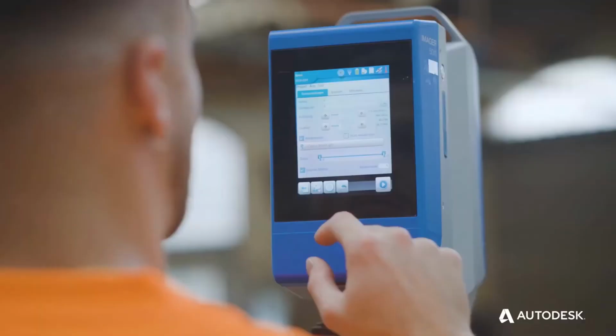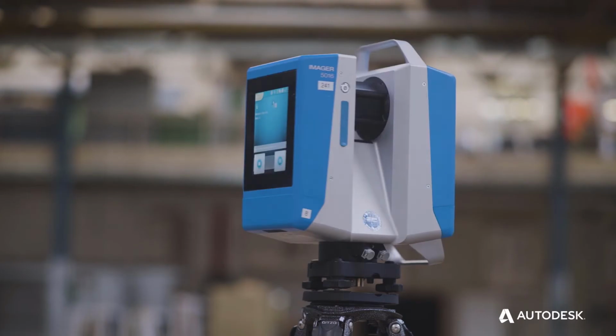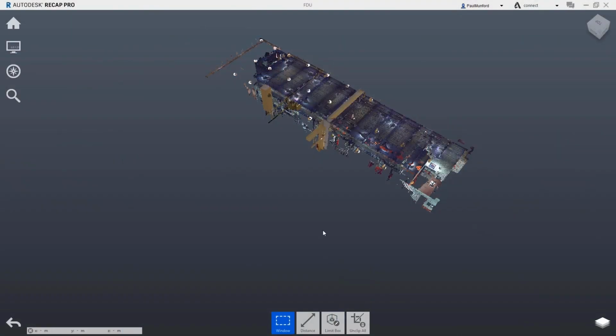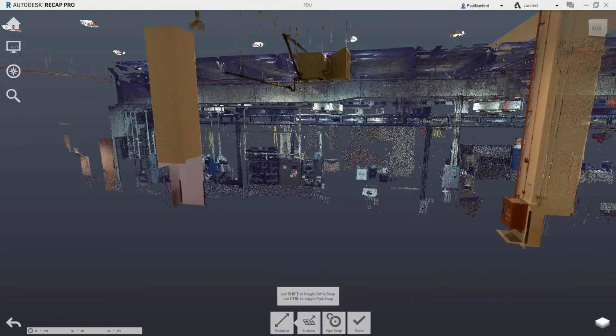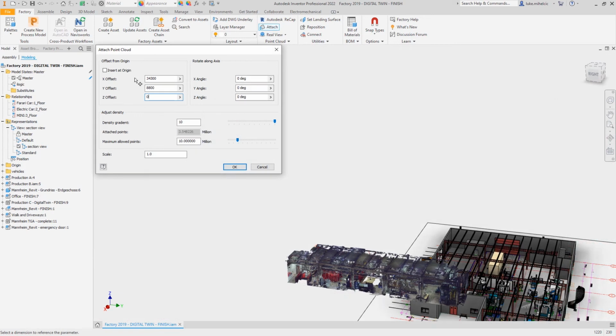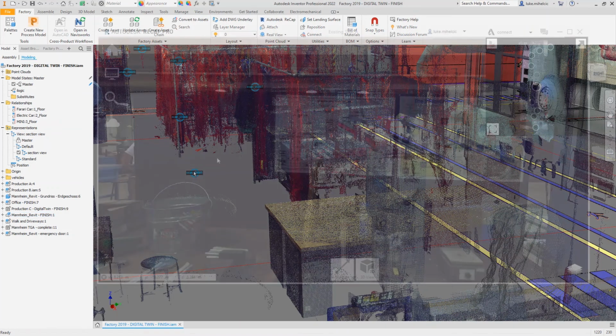So I'm going to drill down into one specific aspect of Navisworks, and that is working with point cloud data or reality capture. It all starts with a 3D scan. You may be a building owner and you want to make sure that new equipment coming in is going to fit properly, or you may be an equipment manufacturer and you need to understand existing conditions for your installation. Scan data can be viewed just like any other 3D model and measured just like any other 3D model.